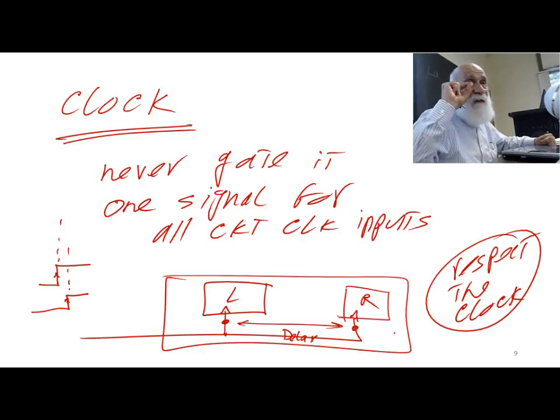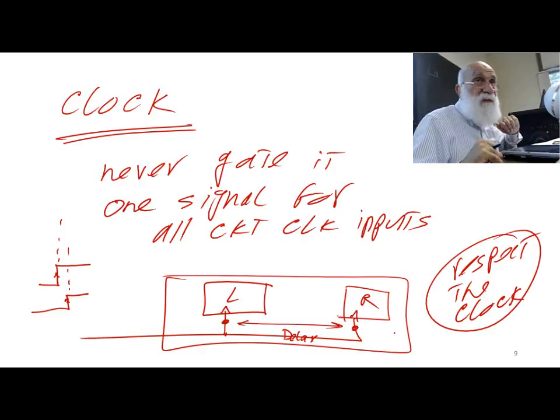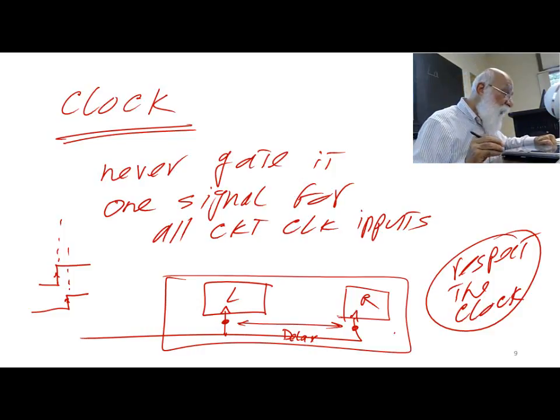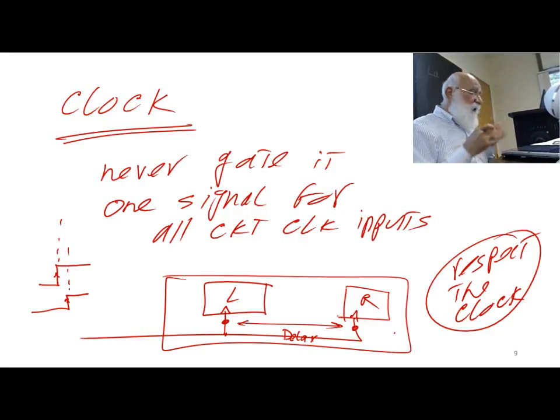And then at the very end, I tie the set, reset, and the clock to the external circuits, and none of those have ever participated in the logic of my design procedure. All right, this is fine, and we will be continuing the same topic of counters and then going into state machines next time.